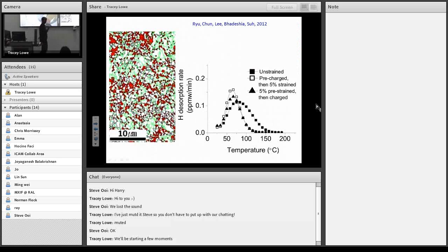The next complication when it comes to complex microstructures is that if you pull and you've got a large concentration of hydrogen in the austenite because you've saturated the sample, the solubility of hydrogen in austenite is greater than in ferrite, and the austenite transforms into martensite. You've got a very large concentration of hydrogen in the martensite, and it's going to zip through the structure. So suddenly the diffusion coefficient will be much larger because you've changed the crystal structure. And indeed, that's what you find.